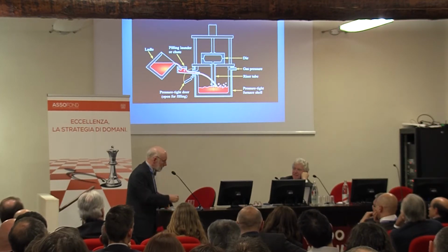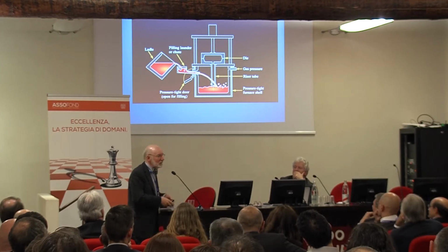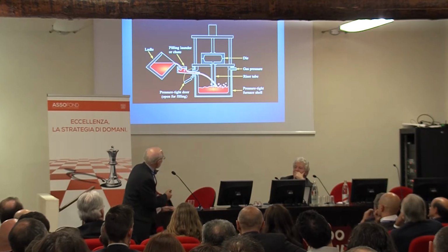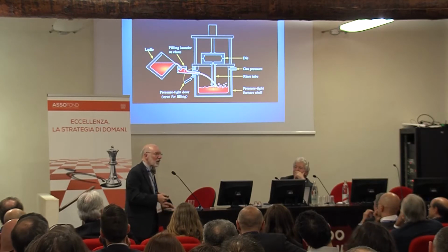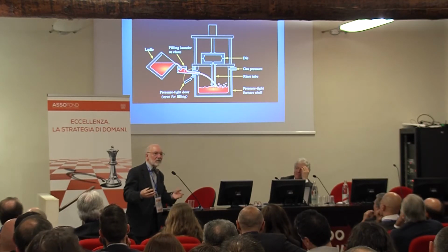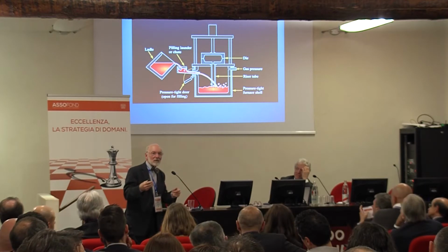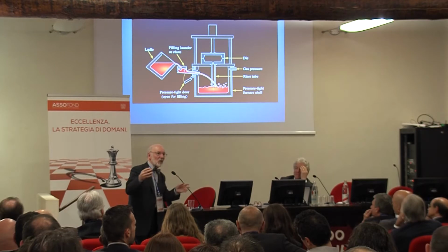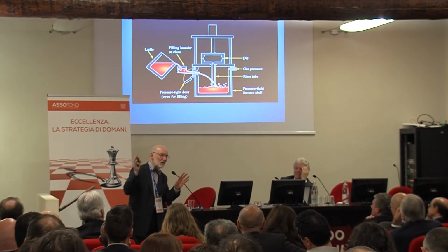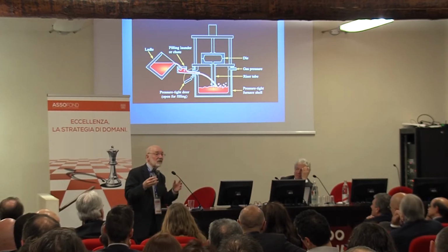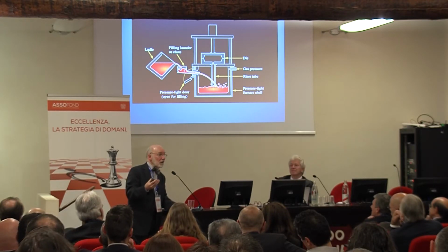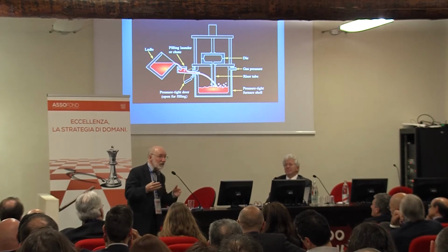Now, there are some better forms, and you all know that you can swap the furnace around. But the whole business of casting into a die and having to wait while your metal goes solid, with a wheel, if you're lucky, you can make a wheel every 3 minutes, or if you water cool your die, which I hate, you can get down to 2.5 minutes. But with sand, if this was sand casting, we could make a casting every 45 seconds.